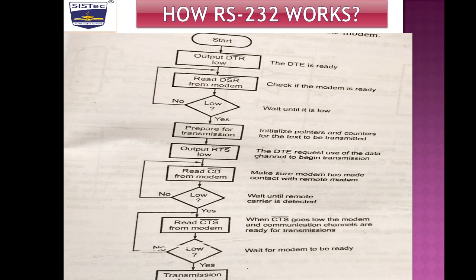This is the flow chart which shows the handshaking process. We use the asynchronous mode of transmission, so handshaking is required. Basically, in asynchronous transmission there are three modes used in RS-232 standards: no handshaking, hardware handshaking, or software handshaking. This is the flowchart of the handshaking signals.